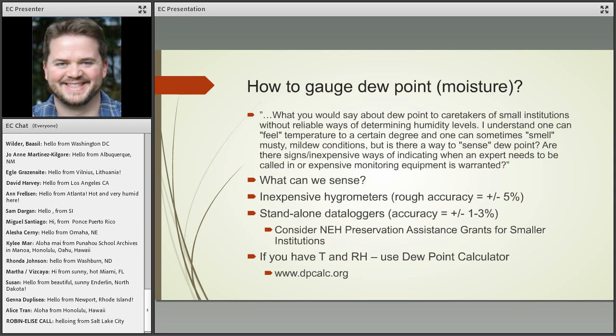If we walk into a space and you get that feeling of it's awfully humid or it feels kind of clammy in here, if it's cold and damp, absolutely take that as an indicator that the moisture content may be off slightly. What you're actually sensing is the relative humidity, not the specific moisture content. But that indication that the relative humidity might feel high is worth then going and trying to track down information for what the actual measure might be.